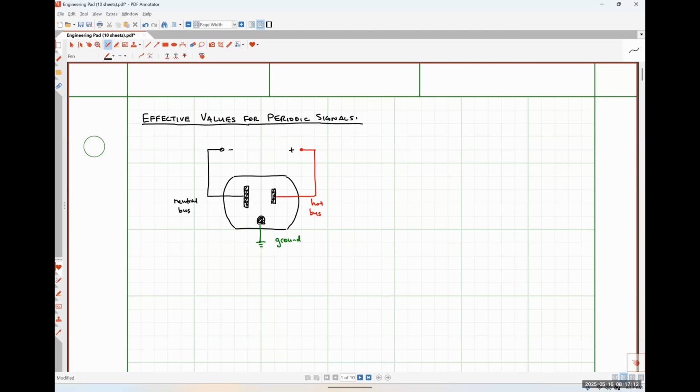So as our voltage as a function of time, if I'm remembering correctly, my math might be slightly off, it'll come out to be, I believe, about 169.7 cosine 120 pi t plus whatever phase we happen to have whenever we start looking at our signal, okay?